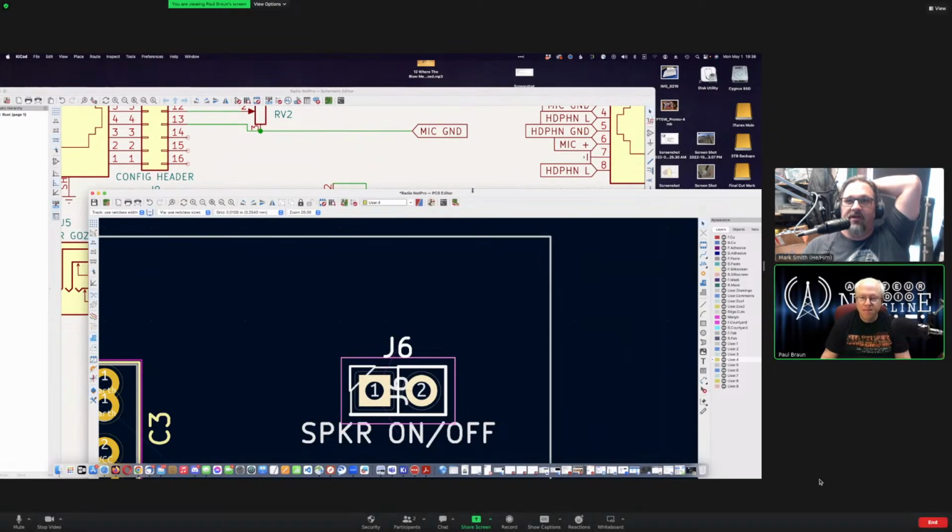Those are labeled 1 and 2, which is different. So we need to have either a schematic outline that is labeled 1 and 2, or a board footprint that is labeled A1 and B1. We need to go one way or the other.